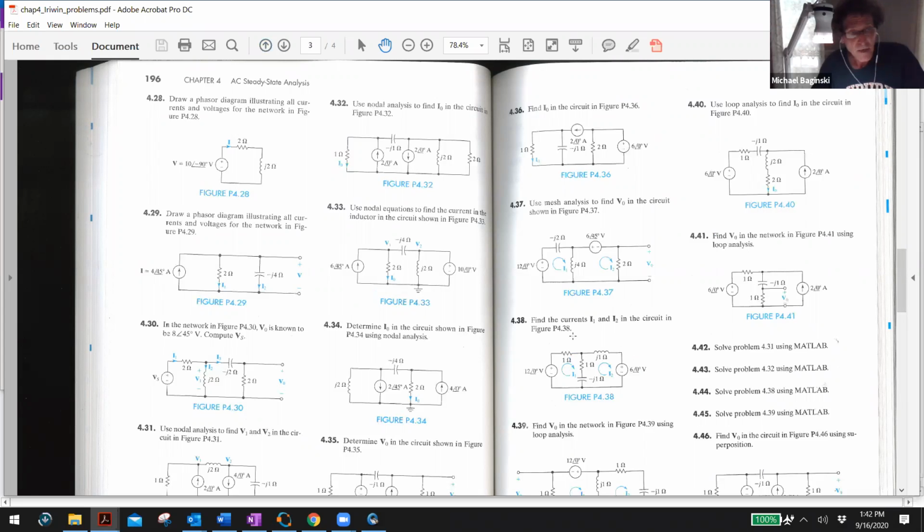Now here, this is kind of straightforward. You're going to go through and just write the equation, summing voltages around this closed loop, then summing voltages around this closed loop, set both equal to 0, right? And then solve. It's going to be a 2 by 2. But it's a complex matrix. That's the thing I've got to get in your head. It's no longer just real numbers.